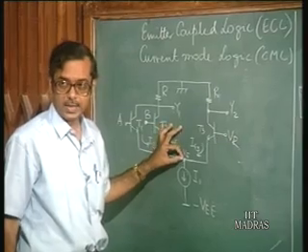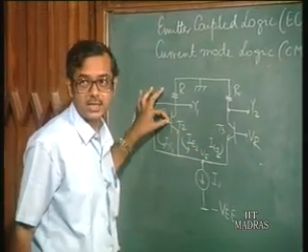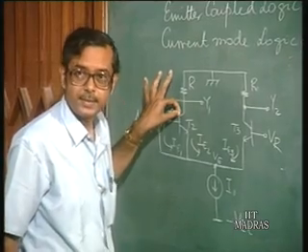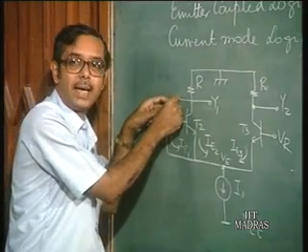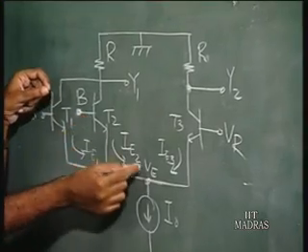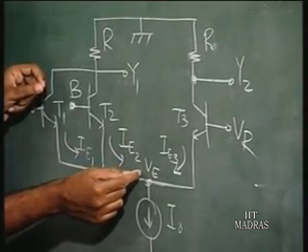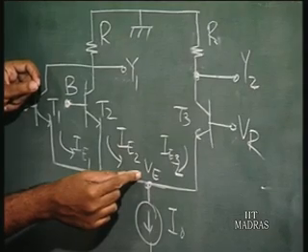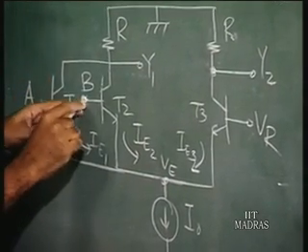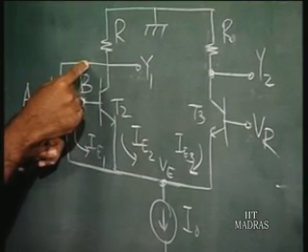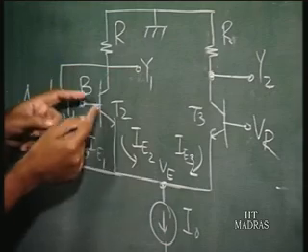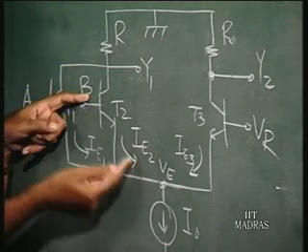That is going to occur when the input voltage is at its maximum. When the input voltage goes to the maximum, that input voltage minus V on is going to be the maximum value you can have at the emitter point. So the maximum value you can have at the input is Vr plus half V on. So if this is Vr plus half V on, the base emitter drop is V on.